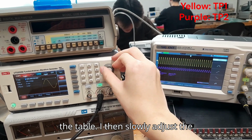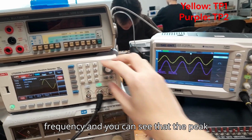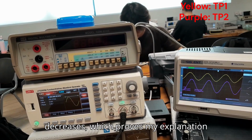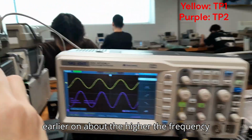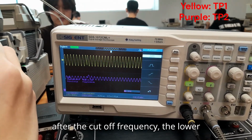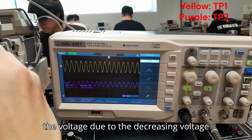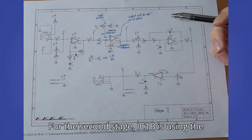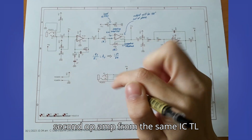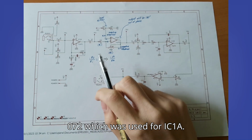I then slowly adjust the frequency, and you can see that the peak-to-peak voltage of the purple graph decreases, which proves my explanation early on about the higher the frequency after the cutoff frequency, the lower the voltage due to the decreasing voltage gain.